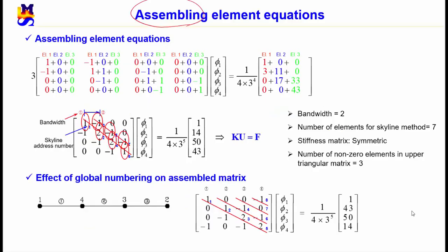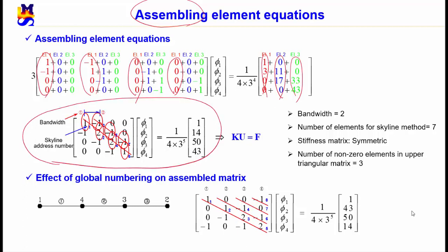This slide shows an example of the assembling process of the finite element model we constructed already, for practicing finite element analysis by hand calculation. In this equation, each color is for an element. That is, red color is for element 1, blue for element 2, and green for element 3. Finally, we obtain this finite element equation ready to be imposed essential boundary conditions.